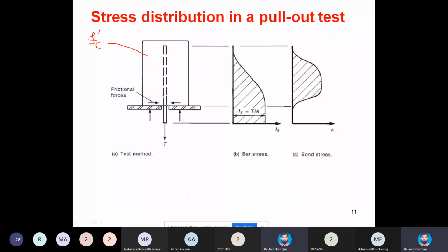This is a cylinder, and this cylinder has some concrete of certain compressive strength. Once you cast the concrete in the cylinder, along with that, you place a bar inside of known diameter, maybe number 25 or number 19, up to its known embedment length inside the cylinder. You know how much length is inside the cylinder. The cylinder may be 6-inch diameter by 12-inch height, 150 by 300 millimeter, and you kept 50 millimeter or more below the tail of the bar. So you are not actually providing the bar to its full depth embedded in the concrete.